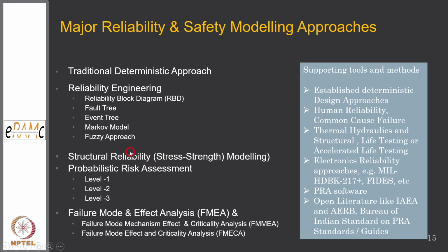There is also one more reliability metric that is not time varying, where reliability is not a function of time but a function of cycles. Like if I have a relay, how many times it has gone on and off in a year will determine its life. So the number of cycles could also be one of the metrics for reliability, and it is used in the PRA model. It is nothing new as such.